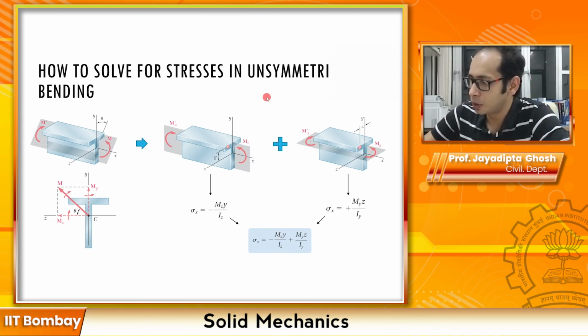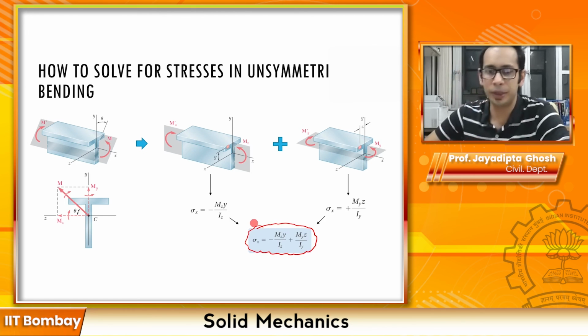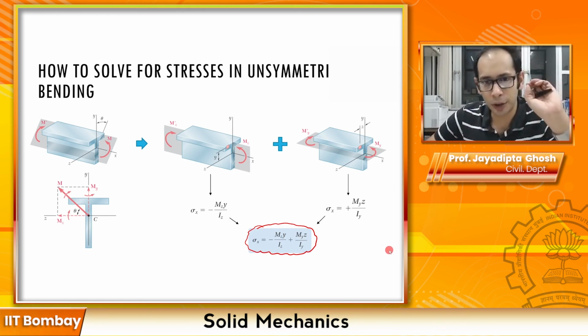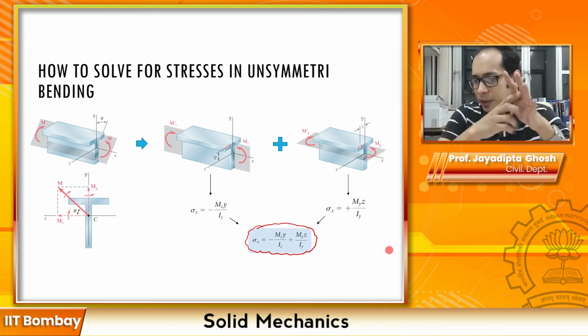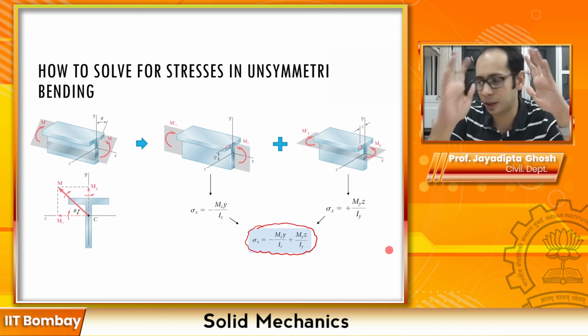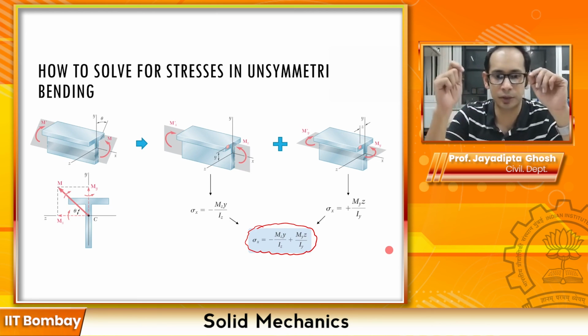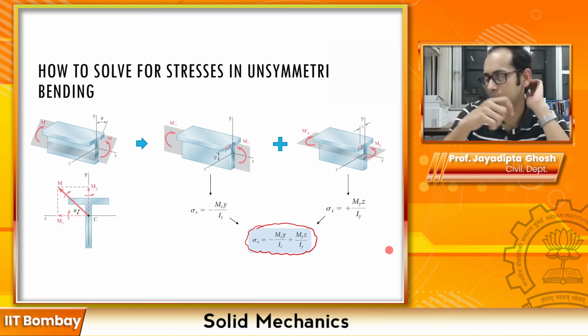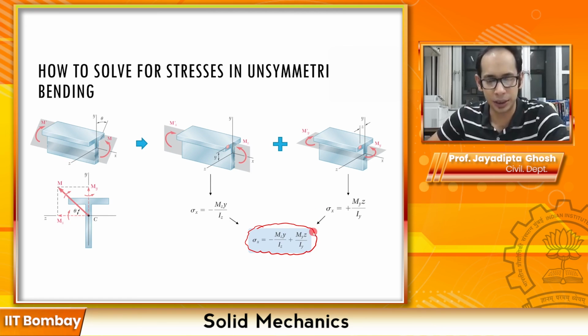So here what it says is that for a point in your beam, this is how we are going to calculate the moment. Now again, don't be too bogged down by the signs. If you're given a problem on unsymmetric sections, then just understand that you have to keep a logical track of where is going to be compression, where is going to be tension, and you subsequently add it up, you subtract. But that is not to say this formulation is incorrect. Sign wise, it's a correct formulation.